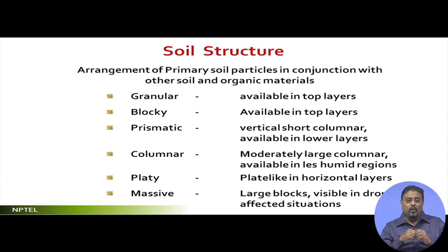But in the black cotton, what happens is this particular soil type is highly susceptible to expansion and contraction by the addition of water, and the soil particles are very fine in size, that means more of clay within. So in such a case, the structure of the soil is very soft.